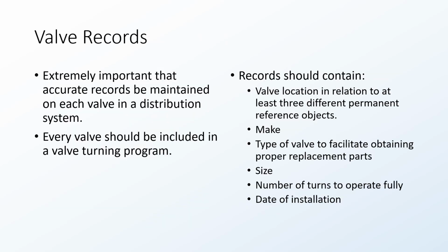You want to maintain really good records of where your valves are. This can be very important because most main breaks don't happen in the middle of the day when you have people available to help you. So having some sort of record that you can access in the middle of the night is going to be important, so that way you can isolate a main in the event of a main break.